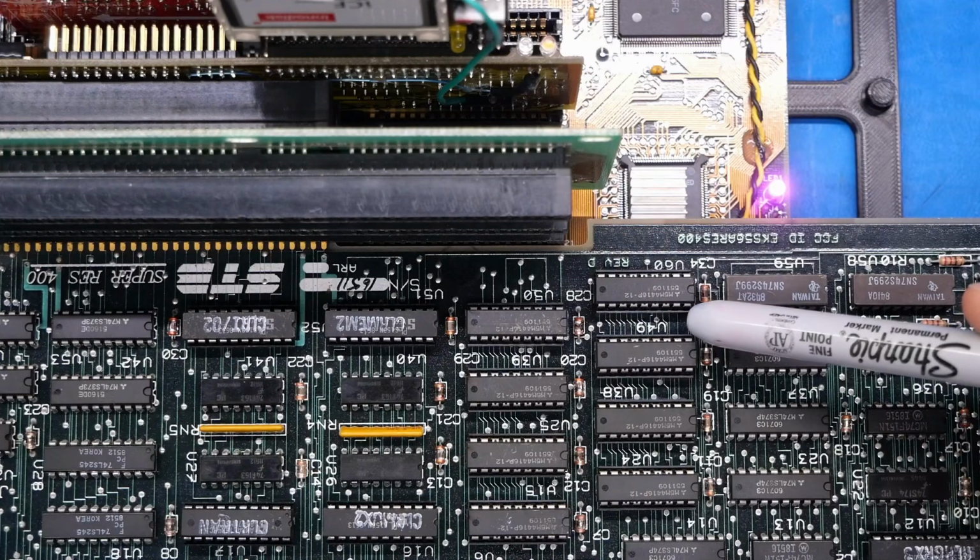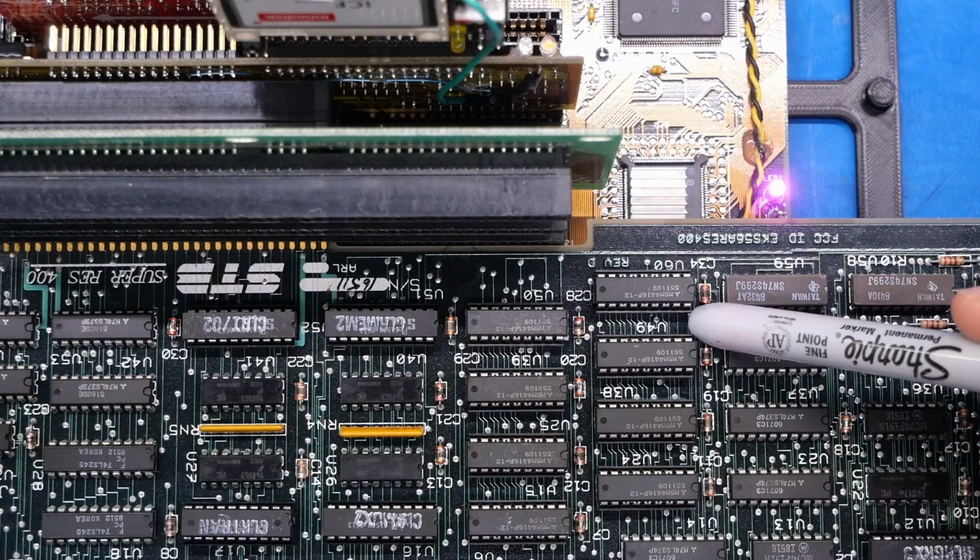Now the thing is, when we ran CheckIt, it checked the memory, and it said that it was fine. I happen to know that the way CheckIt checks the memory on a CGA card is it just fills the 16K with a bunch of data and then reads it back. And I think it alternates the bits a little bit, something very simple. But it essentially is reading and writing directly from the RAM on the board, because the RAM on the board is not only available for display out to the monitor, but it's available for the CPU to read and write from at any time as well. And CheckIt is telling us that the memory itself is totally fine. The CPU is able to read and write the memory without any issue whatsoever.